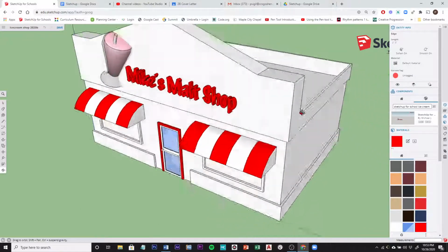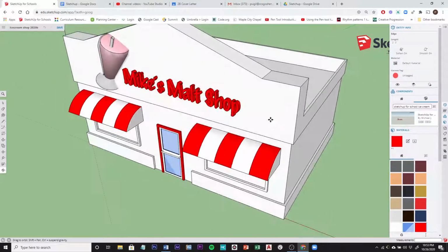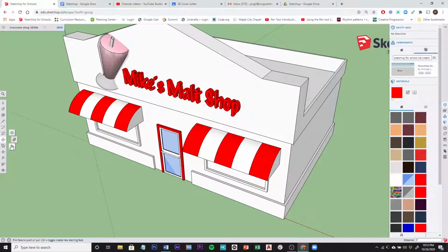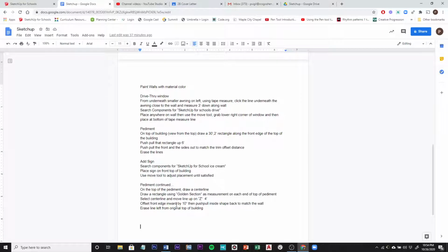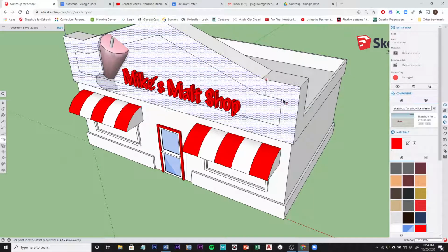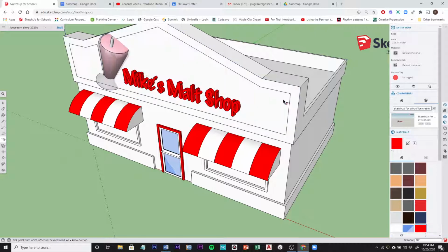Alright, we're almost done with the design part of the main building. The last thing we're going to do is offset this shape here. So we need to go to the offset tool. It's found where the push-pull tool is, the bottom of that arc. And we're going to select this face to offset. And we want to offset this by 2 feet, I believe. Let me check my measurements. 10 inches actually. So I'm going to offset it 10 inches, 1 0, and then the quote symbol, enter.